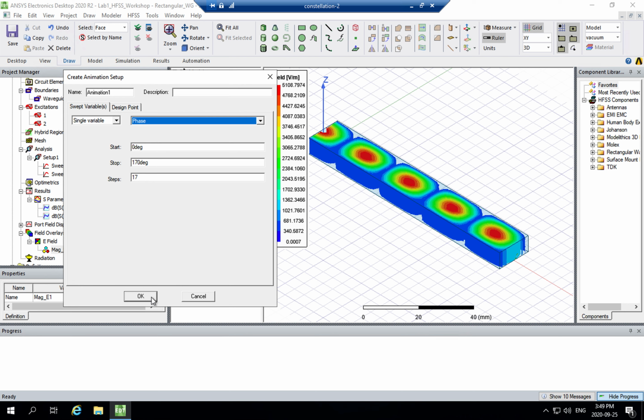Okay, if you cannot see 12, there are two possibilities. Either you did not select save fields in the discrete sweep, or you did not run a discrete sweep. Either way, you can just do it at 16 and it would still be okay. You would still be able to see a similar behavior. So you can just select 16 and follow along for now.